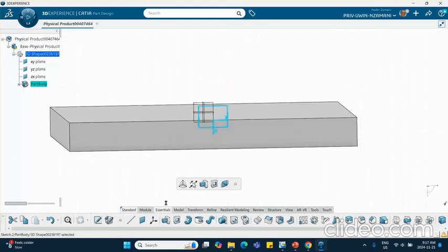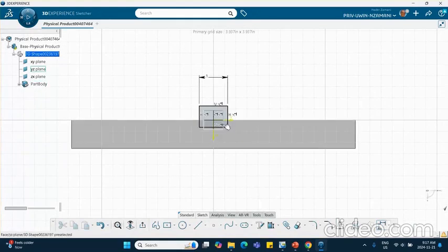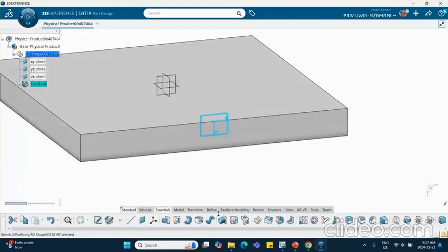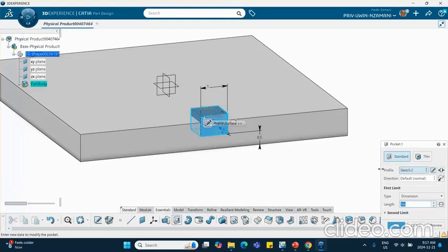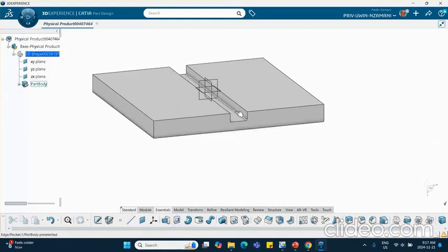Let's exit to see whether that's the right dimension. Yeah, from here to here, I want it to be half an inch. So let's go back there. So the distance from this line, control that line to be 1/2 inch. Okay, exit. And then we make a pocket all the way through, all the way to the last. There. Now, you can make one of these on the other side, but I'm going to do it a different way.